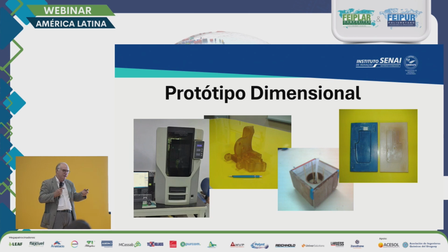So you take this mold that is flexible, you put it on a wood bench that is warped, and then it's going to copy the shape of the wood, and then the piece is going to be deformed, right? To prevent that from happening, we can do a rigid matrix and a mold that is flexible in silicone, okay? That's a solution for large pieces, bigger pieces.